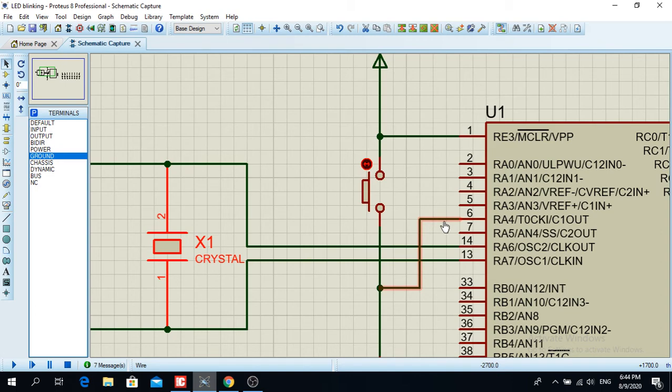This is very important, not just because of this particular example. You can even measure the frequency of an external oscillator. So this is very important to learn. You can either use the clock oscillator, or you can bring some frequency to the RA4 pin. It is your choice. But in this particular example, we used RA4 as the clock source.